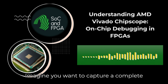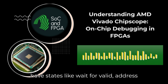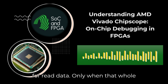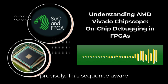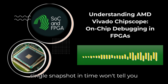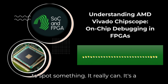Sure. Imagine you want to capture a complete AXI read transaction, which involves multiple phases over several clock cycles. Your trigger state machine might have states like wait for valid, address valid, then transition to wait for ready, read data ready, then wait for last beat, read data. Only when that whole sequence completes does the trigger fire. Wow, so you can define complex sequences. Precisely. This sequence-aware triggering is absolutely crucial for tackling protocol-level issues where a single snapshot in time won't tell you the whole story. That advanced trigger mode sounds like it could save days of just scrolling through waveforms, hoping to spot something. It really can.